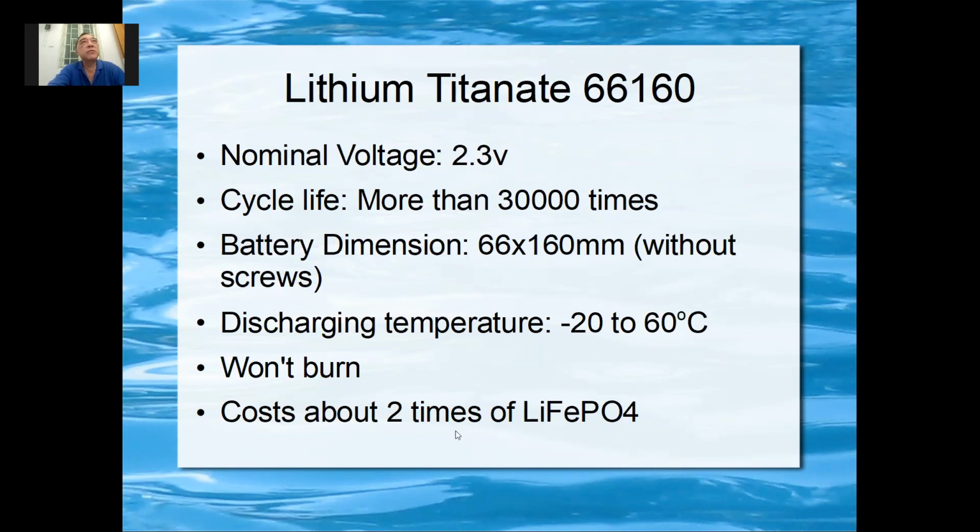Okay. So one good thing is you can drill a hole right through. You can chop it into two pieces and it won't burn. Unlike lithium ion battery, it will not burn. But it costs, let's say, 2 times lithium iron phosphate. Okay, lithium iron phosphate battery and lithium ion are about the same price, similar. So in the long term it is still better, because it costs 2 times and you get a cycle of 30,000 cycles. Practically, you don't need to replace your battery.